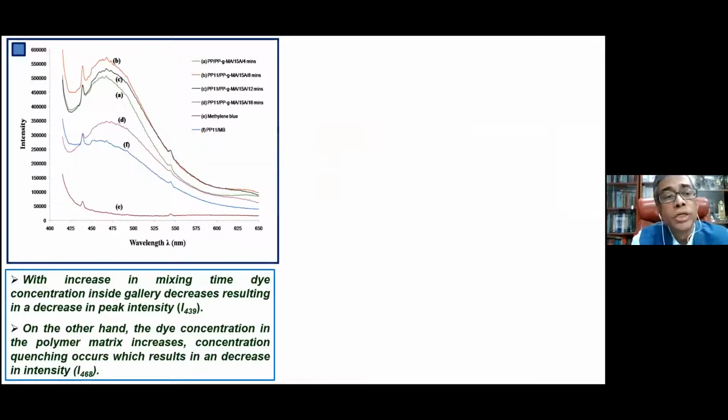So what you do is study the fluorescent emission intensity for different amounts of nanofiller. Here we used a clay, Cloisite 15A, with polypropylene. We used some maleated polypropylene; I'll talk about it later, you need polar group development for this. Then we mix in a little bit of dye as it goes through, and you can see the changes in the peak of the fluorescent spectra.